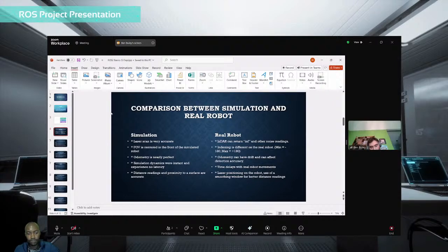The next thing, some of the dynamic movements in the simulation were sharp, instantaneous, while the real robot did have some latency at points. There were movement delays. The velocity thresholds, I had to incorporate that just so it could move properly and be timed properly. For example, my recovery turns needed slightly more time in real life versus the simulation to be working correctly.